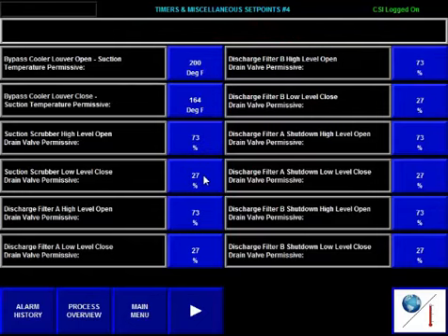This set point is for the compressor auxiliary pump start pressure. When the unit starts, if the pressure is below 48, the auxiliary pump will start. If the pressure is above that point, it will not run.